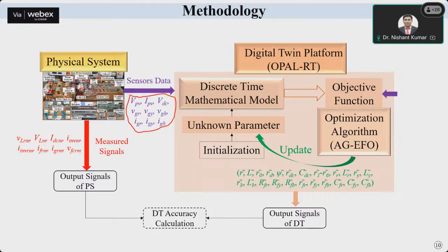Except for this, what are the components you are using there, and if you want to analyze the performance of those components, then the voltage and current across those components, or the power across them, are unknown to you. For example, you are using an inductor just behind your inverter, and you have three inductors, right? Your target is to analyze the behavior of the inductor, so the inductor voltage and inductor current will be required. But you have no idea, because your sensor is not for that. So those will be considered unknown parameters.